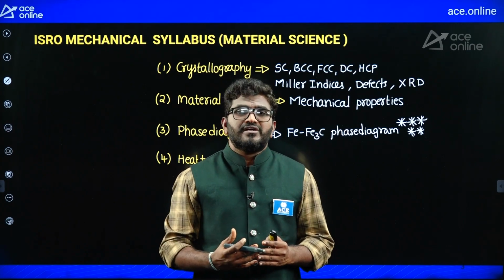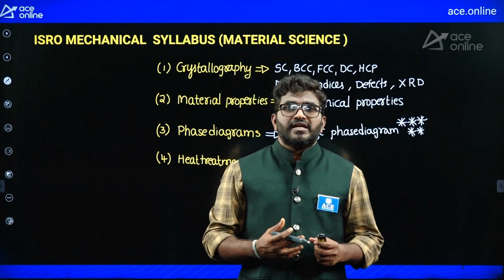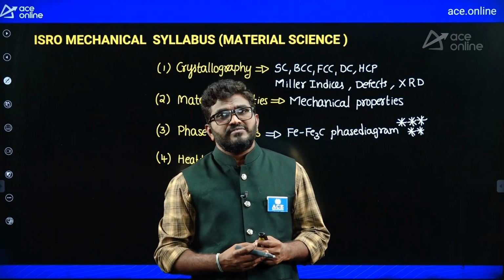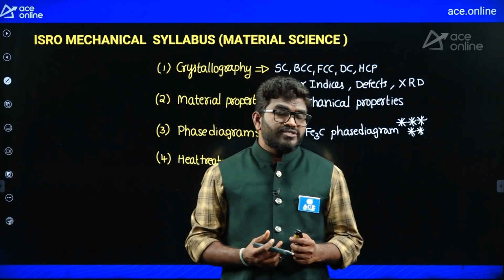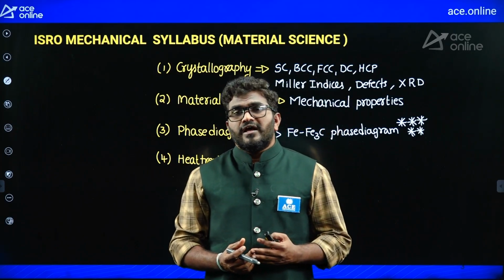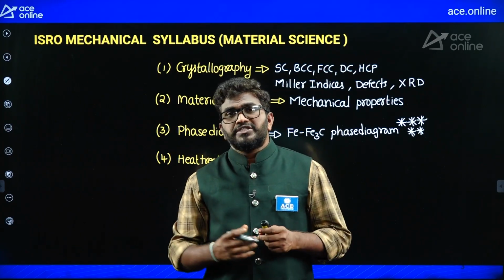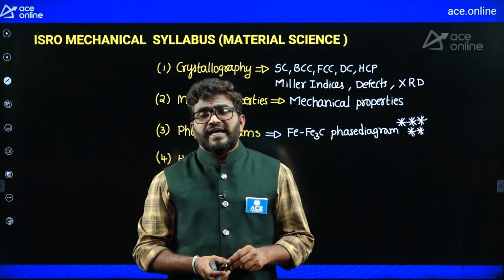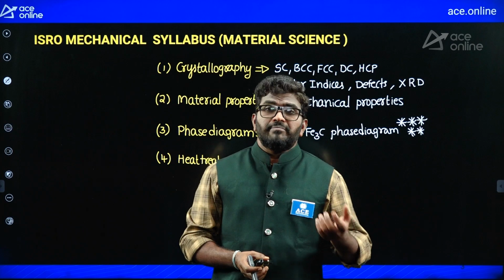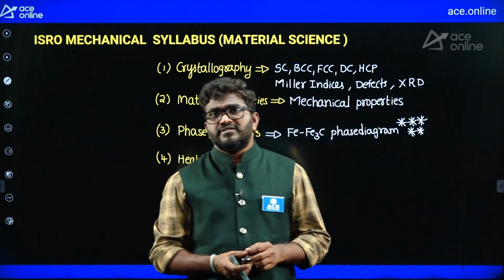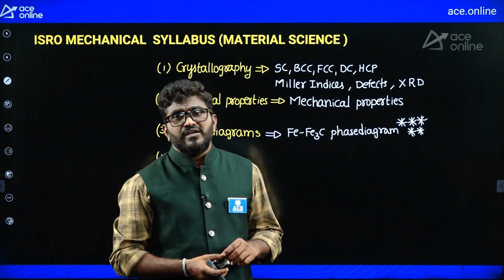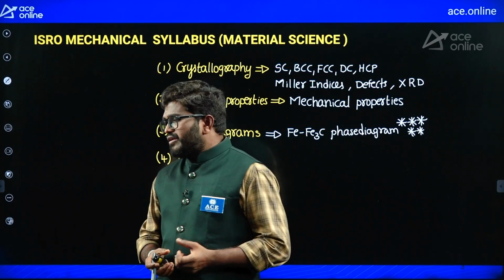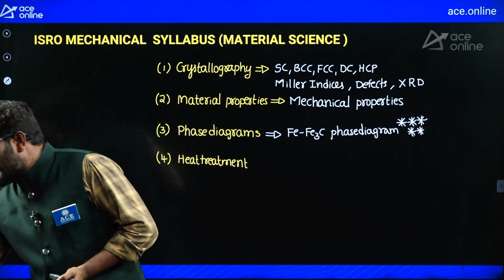different types of annealing process like full annealing, process annealing, spheroidized annealing, diffusion annealing, then the normalizing process, tempering processes, like there are 2 types of tempering process, high temperature tempering and low temperature tempering, and also questions from the time temperature transformation diagram, like how bainite is produced, austempering process, martempering process, and surface hardening processes like flame hardening, induction hardening, carburizing, nitriding, cyaniding. From these they'll ask you the questions.